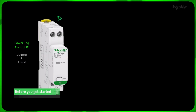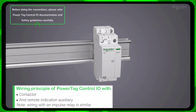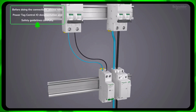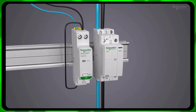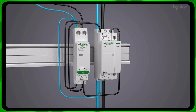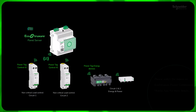Before getting started, please be aware that for this application to function properly, power tag control I/O devices with contactors or pulse relays and remote indication auxiliaries with a proper feedback loop must be installed for switching the loads in your facility. Also, please make sure your panel server firmware version is 2.1 or above.